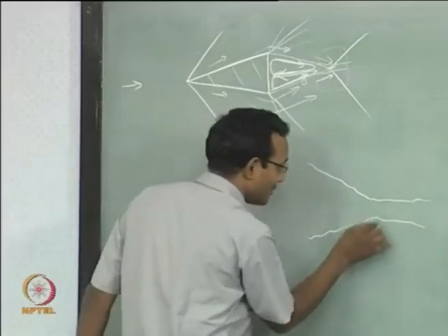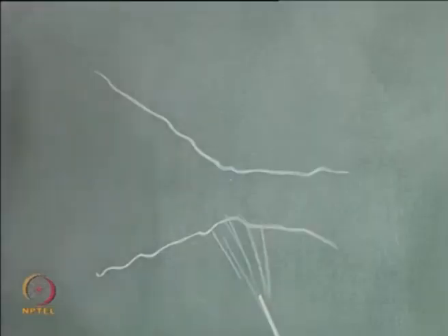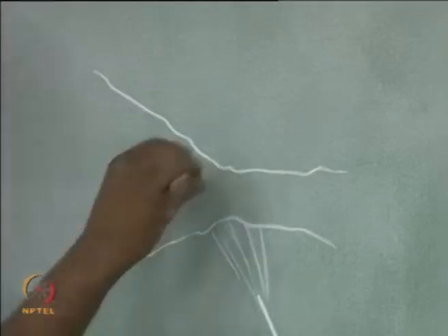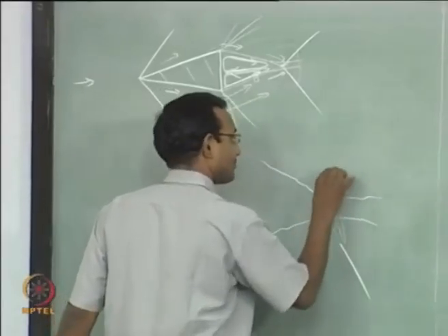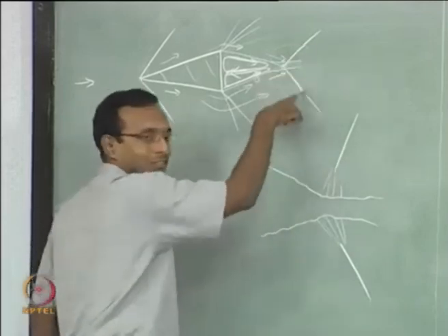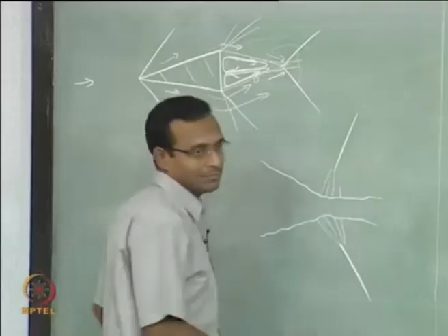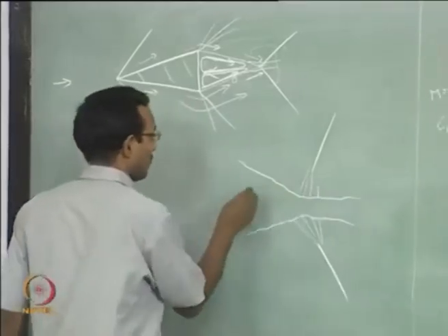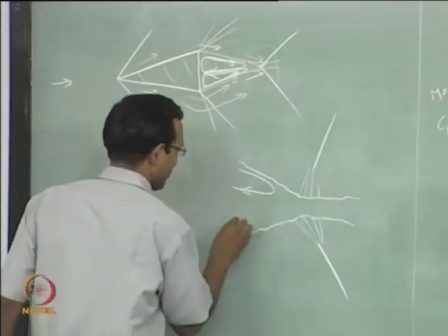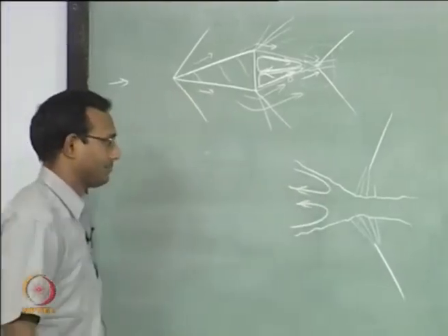So, you are going to have a bunch of waves together, compression waves coming together to form that shock now. This is what will happen there. But this final angle will be the same as what you drew with your simple case. Okay, the final oblique shock angle will be the same. This is the kind of flow field you will get, and here is your recirculation zone. This is what you will get.